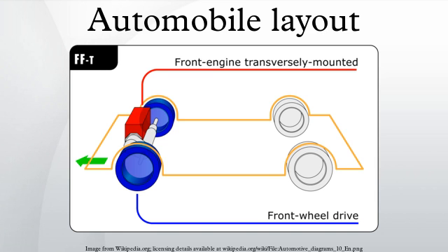The FF layout also restricts the size of the engine that can be placed in modern engine compartments, as FF configurations usually have inline 4 and V6 engines, while longer engines such as inline 6 and 90° V8 will rarely fit. This is another reason luxury sports cars avoid the FF layout. Exceptions do exist, such as the Volvo S80 which uses transversely mounted inline 6 and V8 engines, and the Ford Taurus SHO, available with a 60° V8 and front-wheel drive.